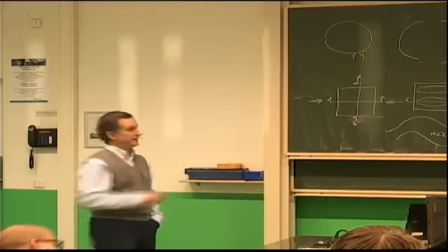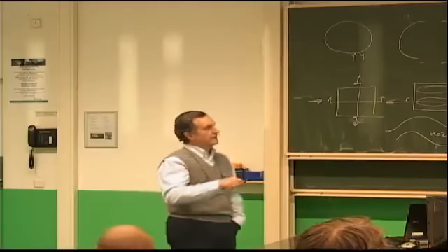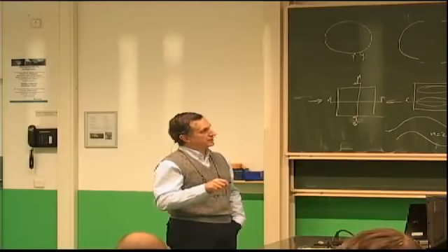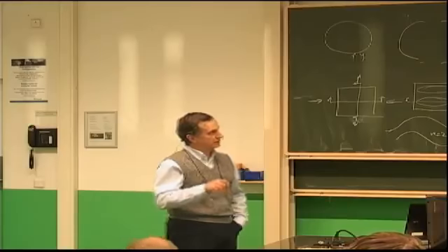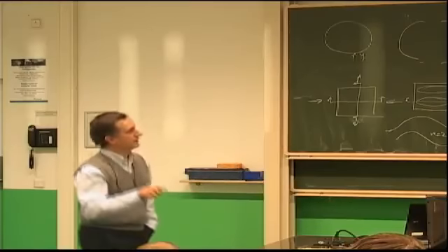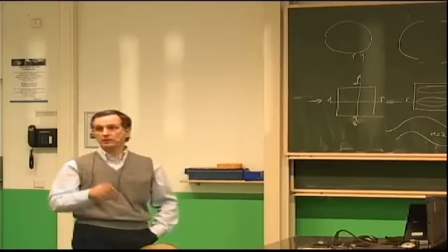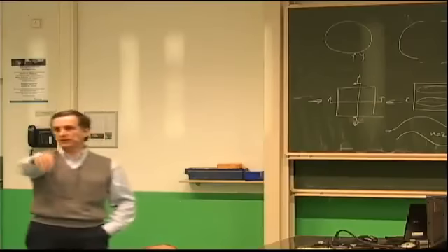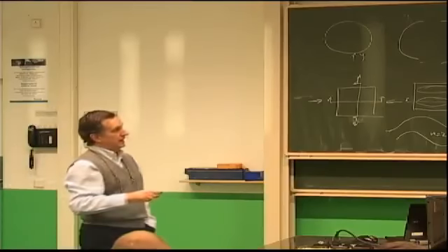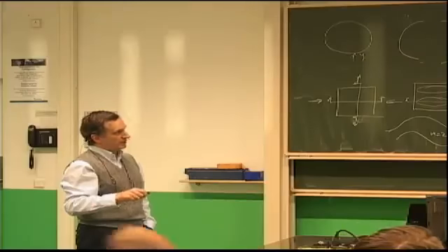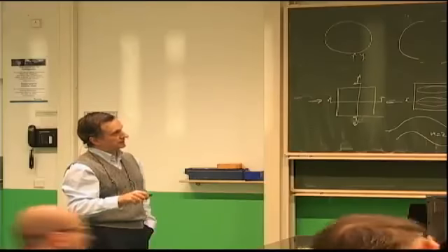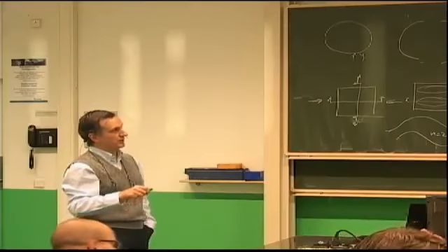Given this D matrix, if my aspect ratio is less than around 1.2 to 1.4, then I buckle with M equals 1, which means I have only one half wave in that direction. Otherwise, if my aspect ratio is between 1.4 and 2.6 or so, it buckles at M equals 2 with two half waves, and so on.